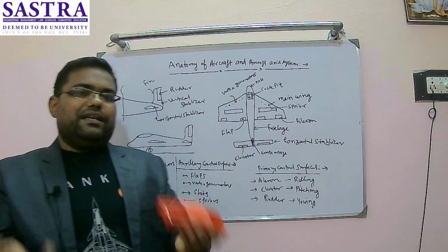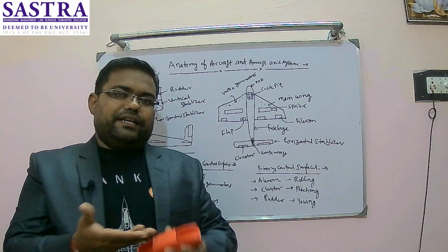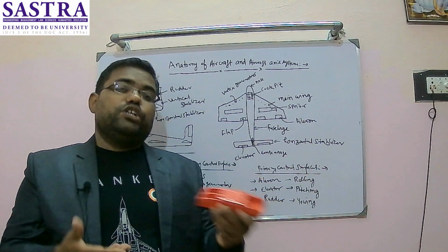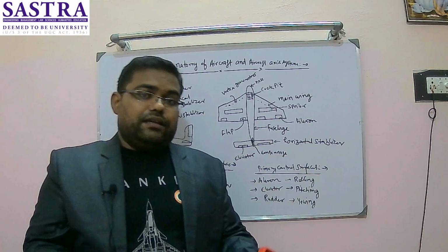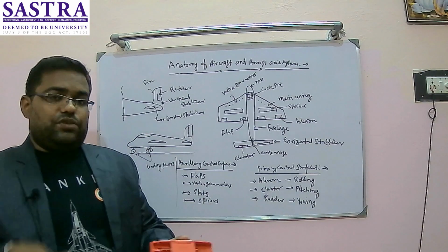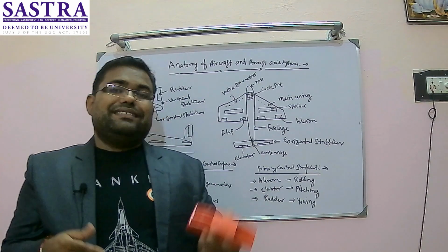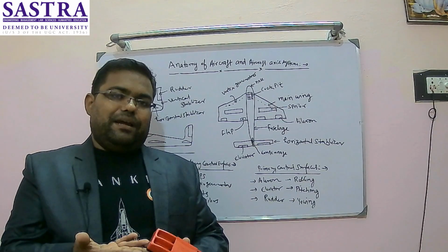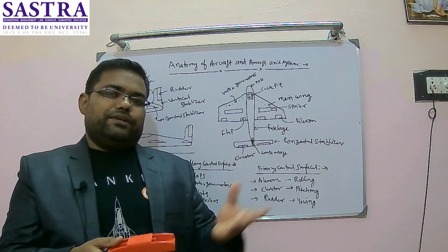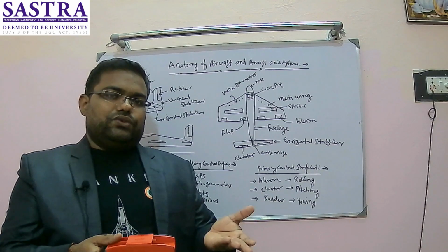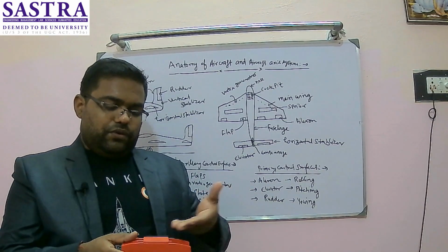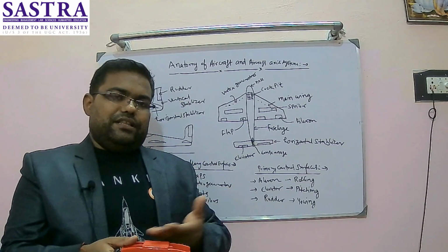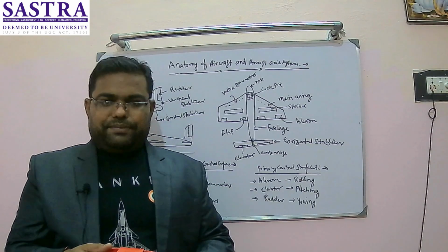So if I want a momentary increase in lift all of a sudden, I can deploy the flaps down when my aircraft is moving or cruising and the speed is increasing. The reverse effect is also possible if my aircraft is decelerating during landing. At that time, if I deploy the flap, what will happen? The flow is already retarded because velocity has decreased. So flow may leave somewhere at 50%, 60% length of the airfoil, and somewhere separation will happen.